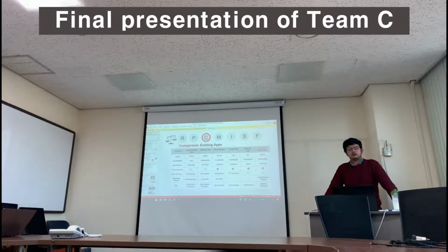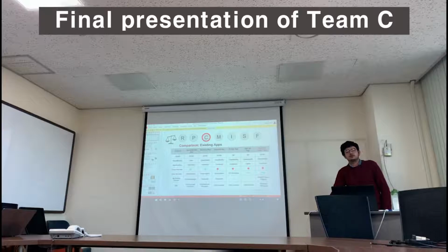You draw the sketch on the XY plane and extrude the sketch. Then the first face is on the XY plane, so we don't select that face. We only select the other face.